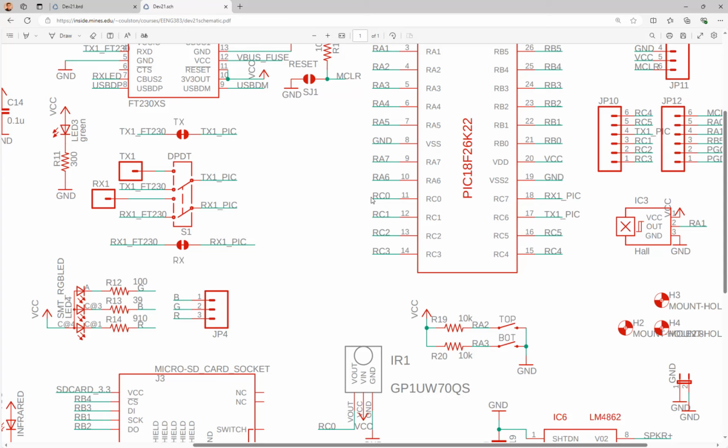So the microcontroller has RC1 here, RC0 here. RC1, I send the PWM pulses to that IR LED, send it to the decoder, decoder comes back, and the digital signal is received by RC0. And then I keep it inside, manipulate it, convert it to a UART signal, and send it through the USB back to the laptop, to the monitor so you can see it.